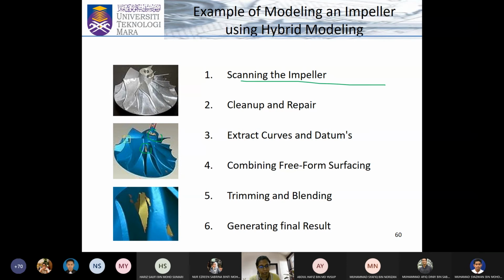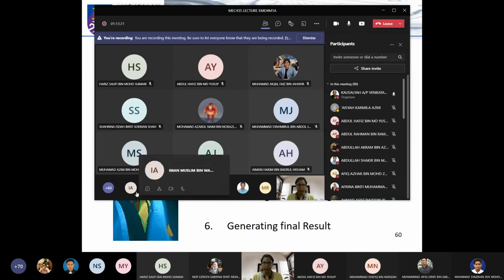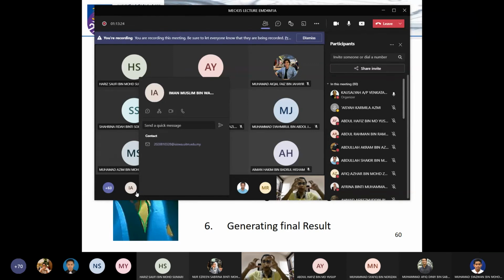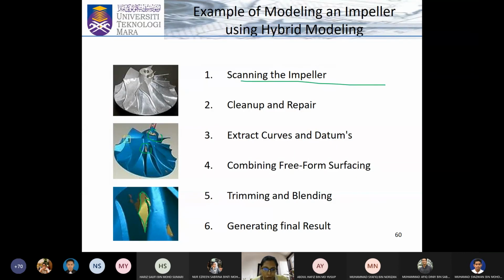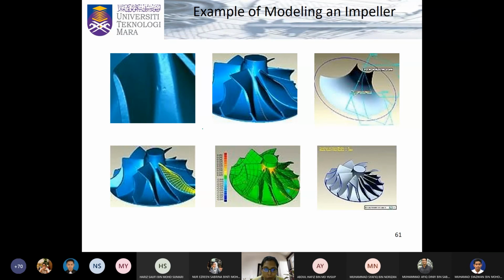What do they do? They trace the boundary, the outline, and once they draw it, they extrude a solid or a surface. You would understand, in all the solid modeling that you have done, if I have a square and I extrude something inside it, the solid and solid merge. It's not like I have double mass inside here. In solid modeling, when I merge something, it's still seen as a single mass. What is extruded outside is seen separately. That's the whole concept here. They will merge and clean up all these surfaces by trimming, blending, and so on. Finally, you will get a smooth surface.